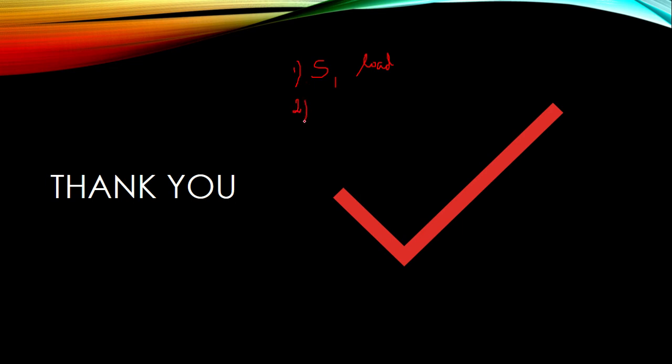The second thing that we saw were the two characteristics of the RF power amplifier. The first one was gain compression and the second one was dynamic range. The third thing we saw was the various distortions that affect the efficiency of the RF power amplifier. So the two distortions were harmonic distortion and intermodulation distortion. Harmonic distortion is due to the presence of multiples of your fundamental frequency, which we saw like this. This is my required frequency. I don't get only this, I get additional frequency components also. So these are called harmonics.